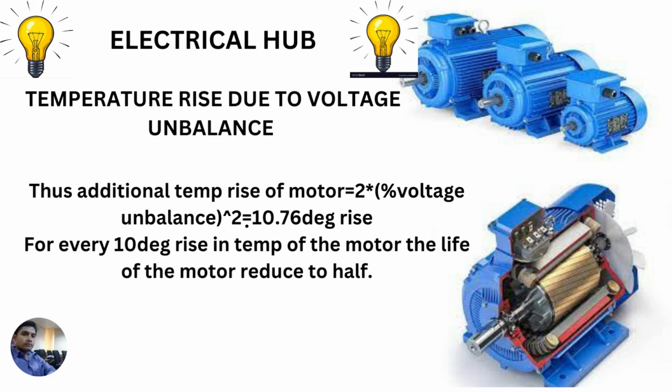As we know, for every 10 degrees centigrade rise in temperature, the life of the motor reduces to half. So, see here, even with a 2.32 percent variation in the voltage, there is a reduction of the life of the motor by half. So, we should try to minimize the difference in the voltage of each phase.